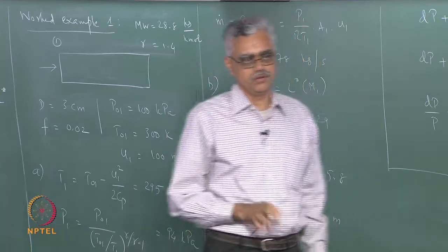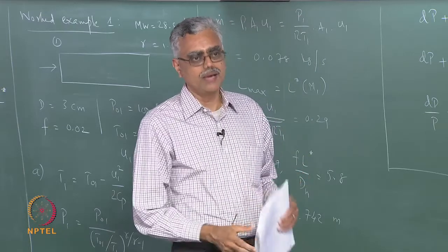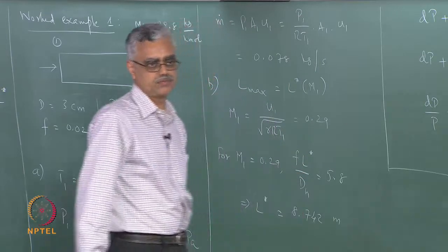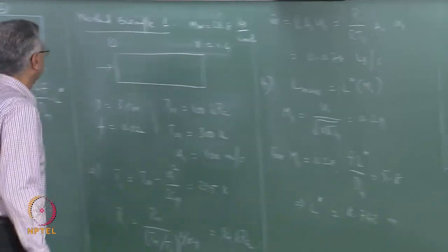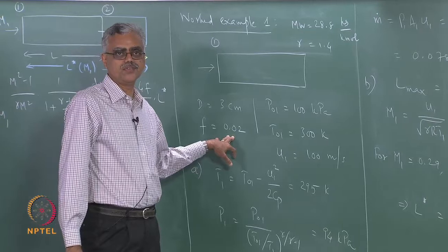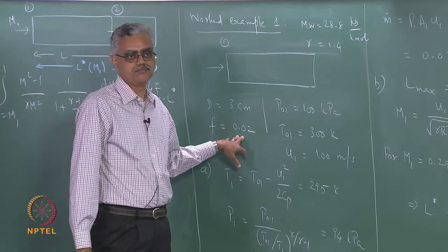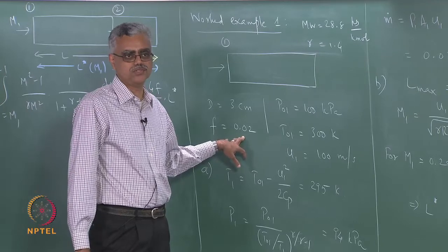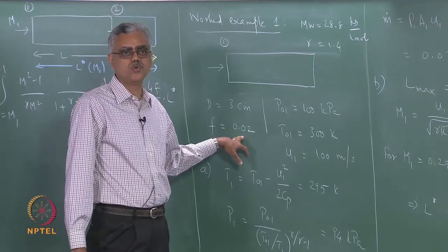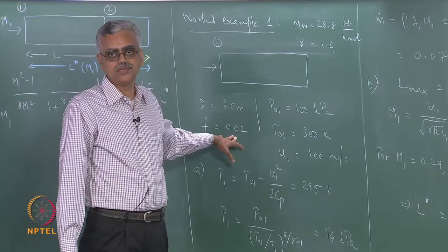So, that is what we are using. Okay. That is why you do not see the 4F there. So, the Manning friction factor for the same case, instead of F being 0.02, would have been 0.005. So, 4 times that is equal to this. But Darcy friction factor is the most widely used. All the correlations give only this, which is why we are using this.